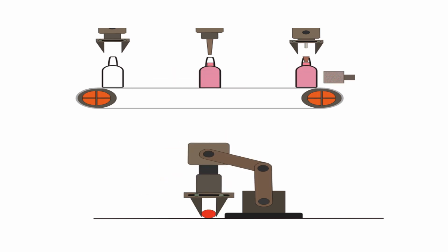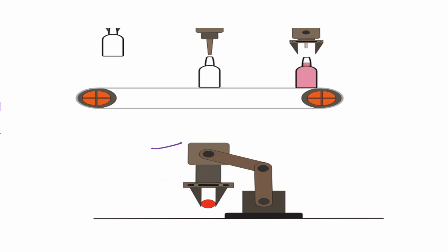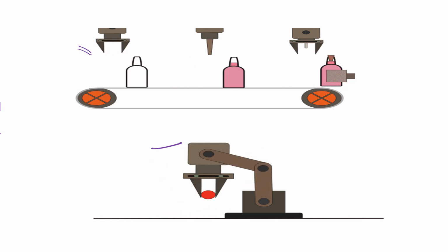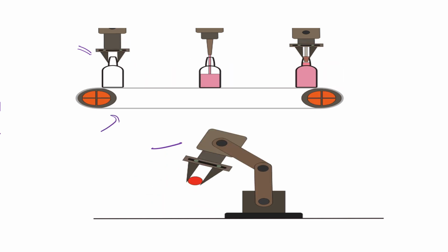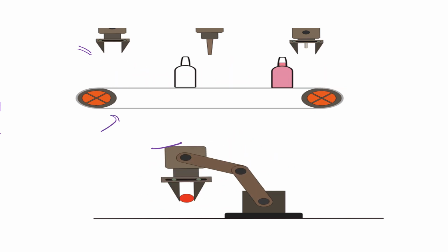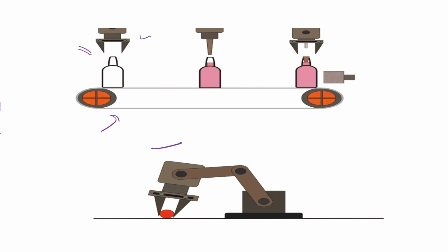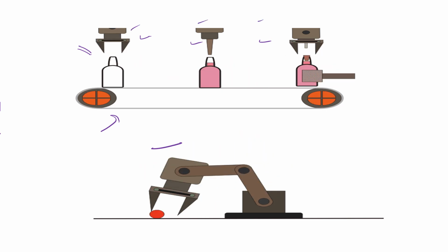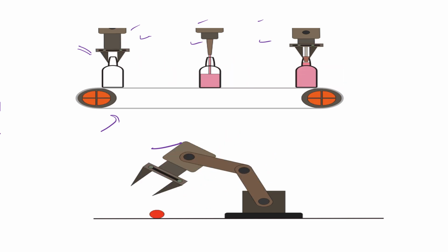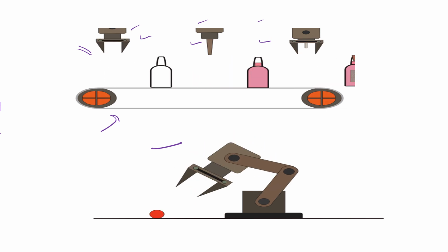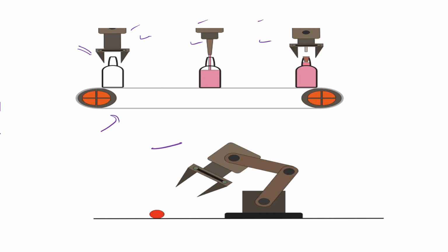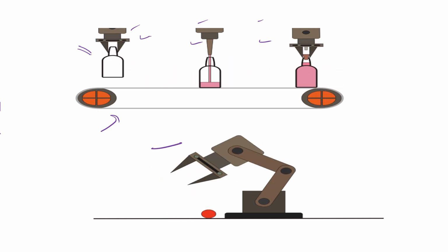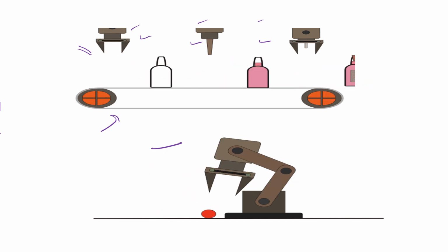Actually, this is the gripper. Here is the end effector gripper. It keeps the bottle here, and then this is the conveyor. Based on the input given, the conveyor moves, based on the speed. The speed is calculated based on this action. Here we have three manipulators with end effectors. The first end effector is a gripper, which will keep the bottle over here, and then the bottle is moved to the next one. Here one more gripper fills it. Once it reaches this point, you have a sensor. The sensor says this is reached, so immediately it is on, and then the liquid is filled. And then one more gripper will fix the bottle cover, and then it moves.